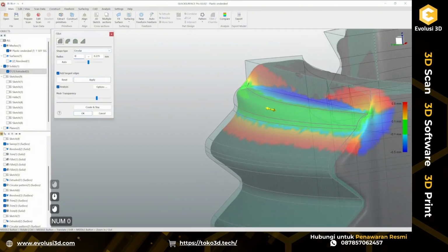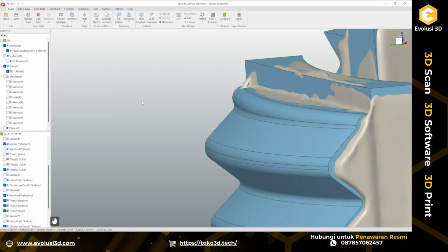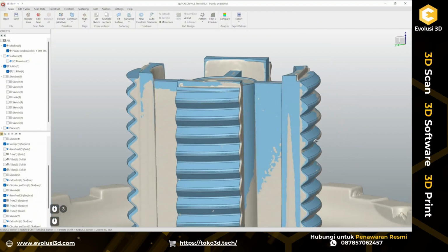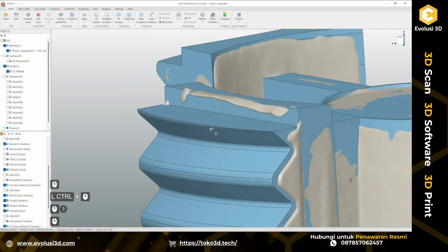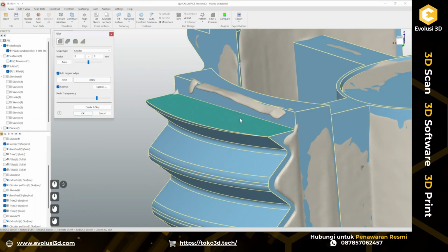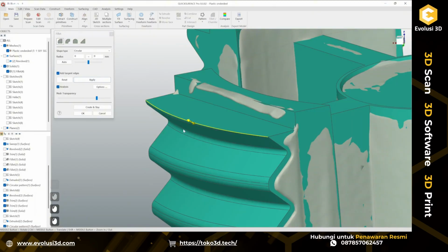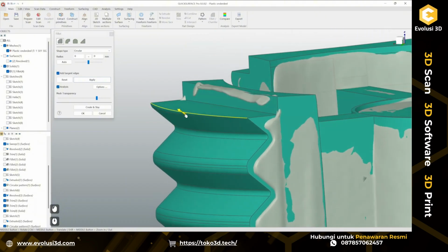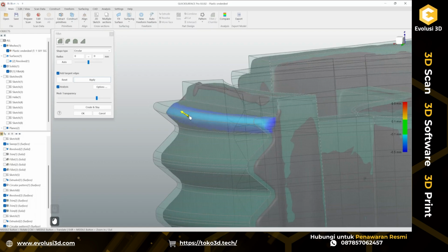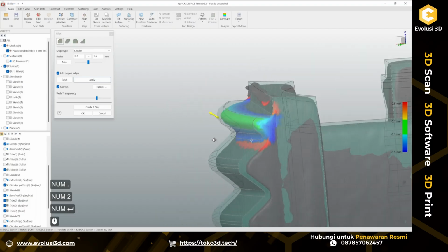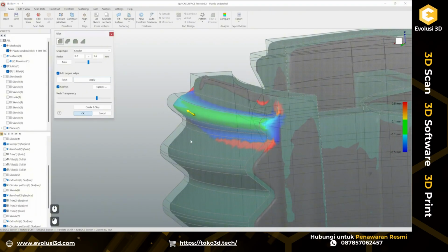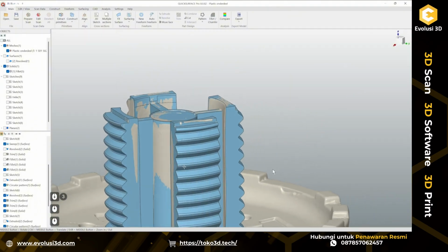Okay, so something like 0.2 looks good. And probably I would need to create the same fillet on this edge as well, but here it might be a problem. Okay, no, it's not a problem. It works absolutely great, and let's just pull it down till we see green, and this is close to the same 0.2, and let's apply fillet of 0.2. Okay, so we're good here.